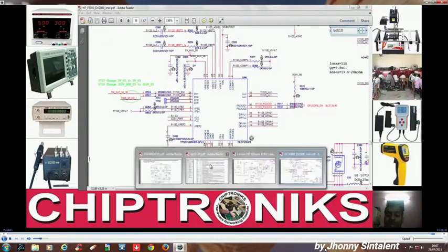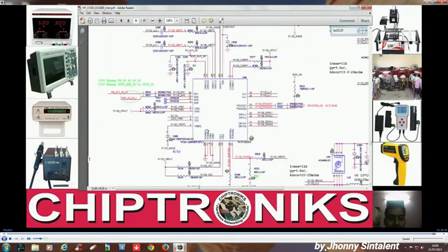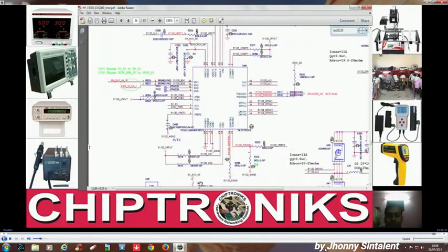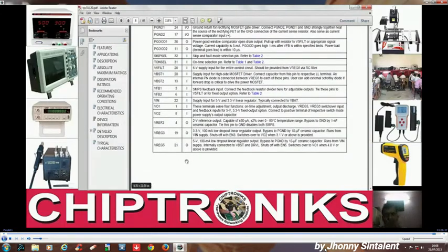So these are the basic differences, and we see V out 1, V out 2 almost the same, no difference between them. But here, V regulated 3 and V regulated 5, these are the 2 LDO, whereas in RT8206LM there was only one LDO.